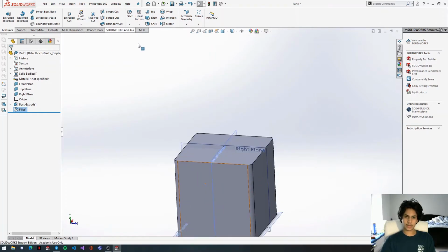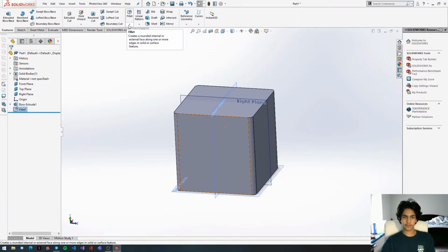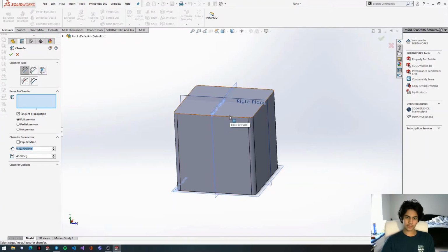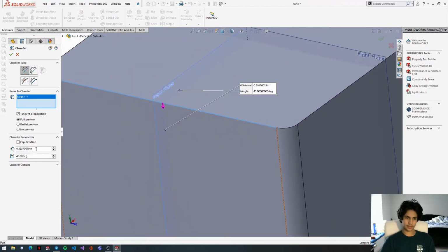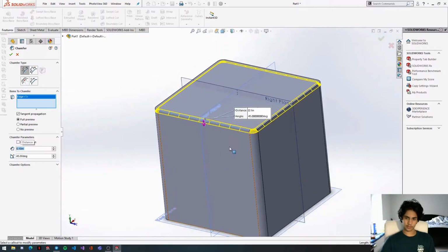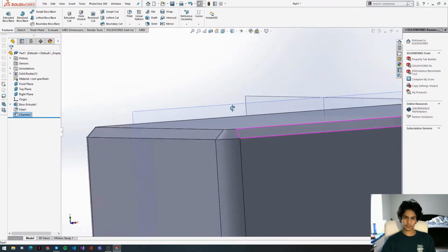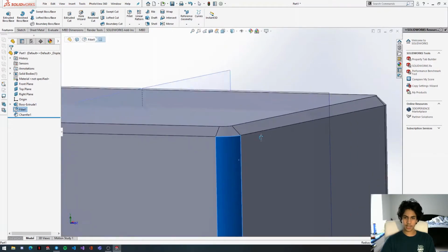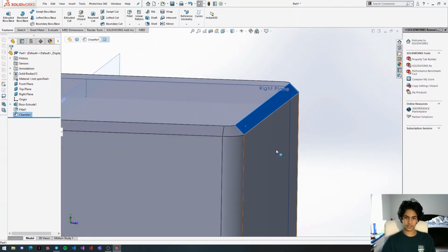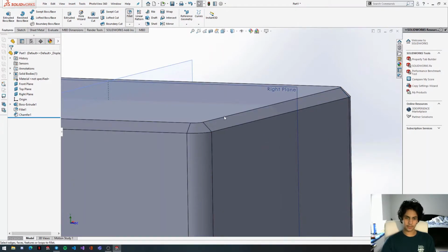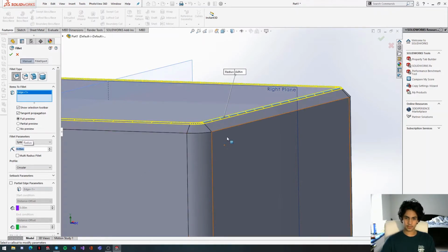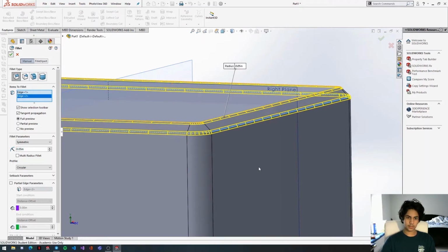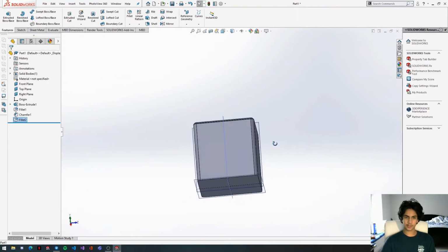And then as you can see over at the fillet tab, we have a little arrow right here. If we click this arrow, we have this button that says chamfer. What chamfer does is it kind of slices down an edge. I can't really describe it, but I'll show it right here. So say we want to chamfer 0.1 inches. Yeah, so this fillet rounded the edge completely, but this chamfer kind of chopped off a triangle from it. And then if we want, we can fillet down this chamfer to make it even more round. Yeah, so we have this weird looking cube right here.